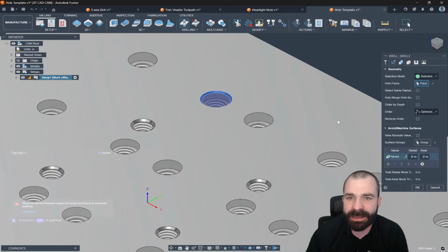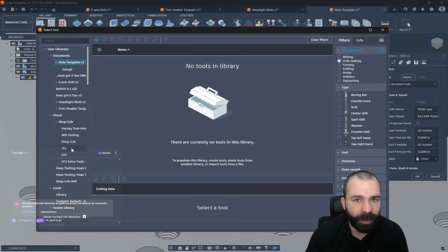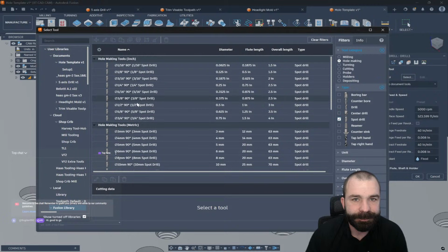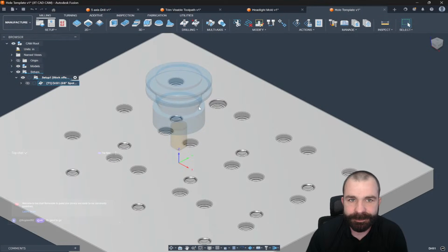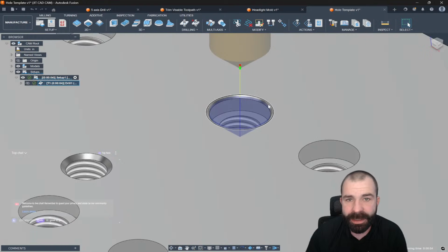So as you guys are going to see me do here, we're going to simply pick our holes. I think I'm actually going to need a bigger spot drill because I threw this part together kind of last minute. 5/8 90-degree spot drill for the top of that guy. Again, as you can see, we've now spot drilled. We actually need bigger than that, it looks like.